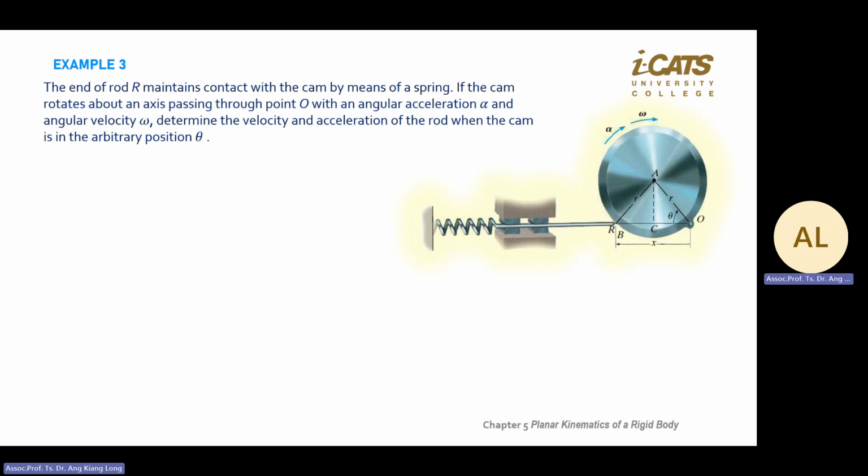So you just imagine when you rotate the cam to the right hand side, the cam will push the pin to the right, because it's a spring. So this rod here is a linear motion, towards the right, positive. So the rod you can write in the A or V term, velocity, acceleration, like what you learned in chapter 1 to 3. It's a linear motion. But for the cam, it's not linear, it's an angular motion. So you need to combine linear and angular motion together.